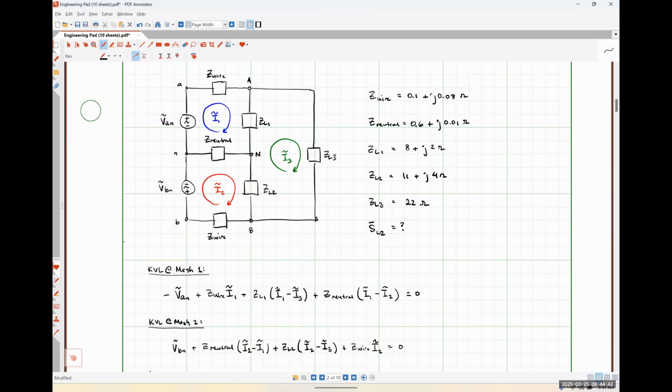How many breaker switches are usually in there? Probably a lot more than 3, right? But all of those breaker switches are going to be connecting circuits either between this capital A and capital N, or capital B and capital N, or capital A and capital B. So if your breaker has 2 poles on it, so if it's twice as large, it is one of those 240. It's a breaker for 240. If it's the single slot, it's a 120 breaker.